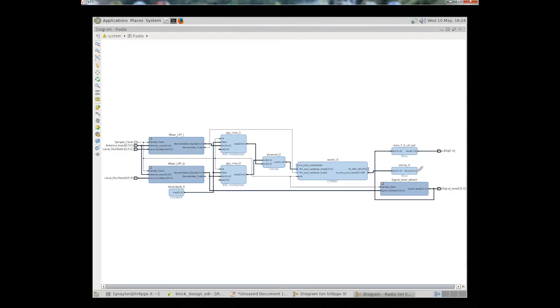and this here is our amplitude signal. Now, because the amplitude is always positive, whereas if we're going to use this to drive a speaker, we really want just the AC component, so we better get rid of the average value here. So we need to do some kind of baseline subtract, get rid of the average value. So let's stick a bit of logic in here to do that.